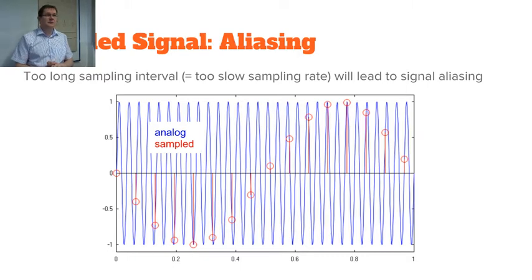Aliasing. Okay, you understand the aliasing, right? We have the real analog signal, and if your sampling rate is too slow, you get that red, slowly varying signal there. So basically, to prevent the aliasing, you need to remove or reduce enough of those high frequency components so you can sample the signal as it is, or go to higher sampling rates.